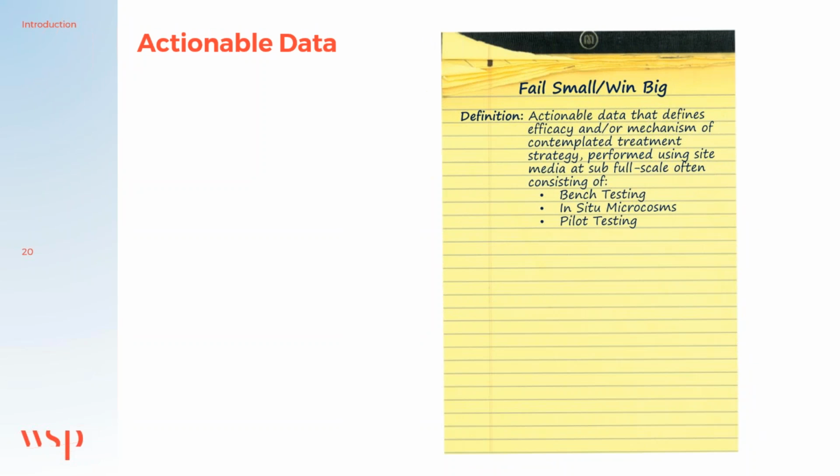At nearly every remediation site I'm involved with, we take a fail small, win big approach with actionable data collection. This typically involves collecting data to define treatment efficacy and mechanisms using site media performed at sub-full scale. In short, I do bench tests, perform in situ microcosm studies, ISMs, or pilot tests for nearly every application.